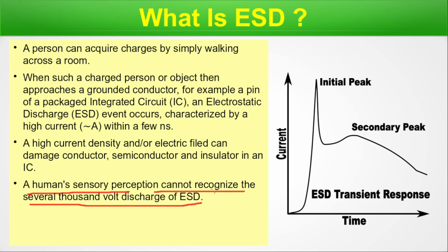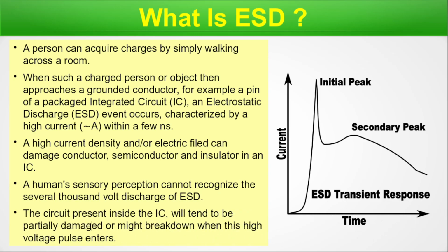So we are not capable of sensing the ESD. That is our incapability. And that's why if you are working in an electronic assembling industry where you are assembling different circuit boards or soldering different circuit boards or doing any kind of activity related to the PCB or actual packaging of the circuit, you are advised to wear an electrostatic strap on each of your two hands separately, so that neither hand is electrostatically charged and the circuit on which you are working does not get damaged. The circuit present inside the IC will tend to be partially damaged or might break down when this high voltage pulse enters. This can happen to the IC we are dealing with, which is maybe inside the PCB or maybe inside the phone that you are handling.